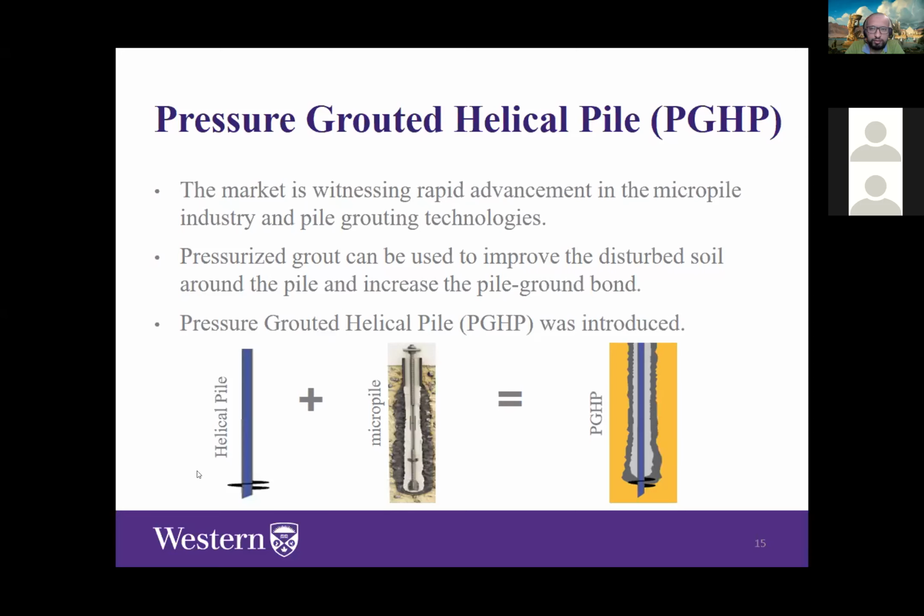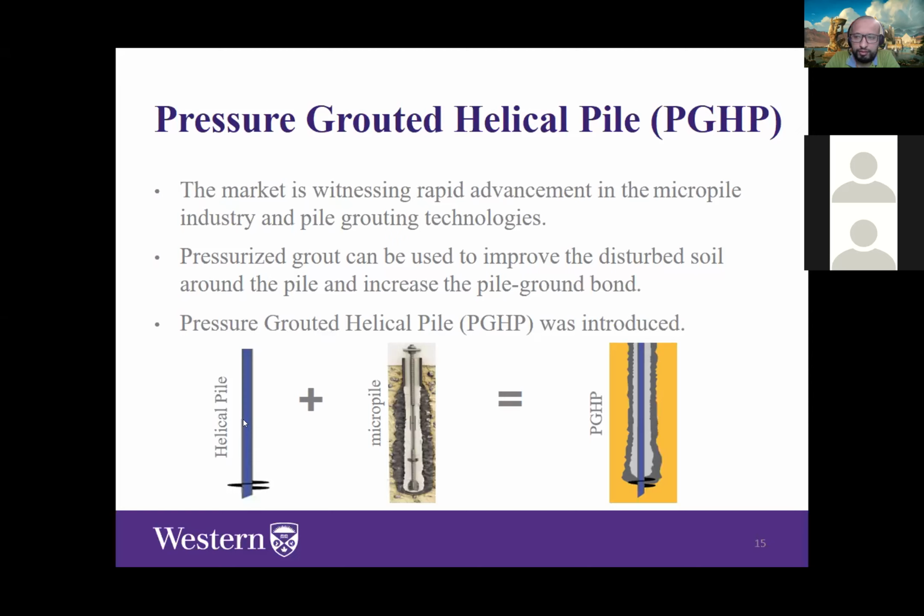Yeah. So just imagine if we have three helices here and we create our grout nozzles on the top helix here. So we will have a much higher shaft resistance actually. So the unit shaft resistance for micropiles is much higher than the conventional concrete piles. Besides, we still have the bearing resistance of the three helices. However, for the conventional concrete piles that you mentioned, we only have shaft resistance along the shaft and bearing resistance